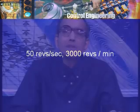And as you know, it turns out that depending on the number of poles on the generator, or the number of pole pairs, because the poles come in north-south pairs, the generator will have to be run at an appropriate speed. This is what actually happens in a generating station, and therefore there is a speed control problem at the generating station itself. The generator, of course, is not driven by a motor. The generator is driven by a turbine, a hydraulic turbine in the case of a hydroelectric station, or a steam turbine in the case of a thermoelectric or thermal generating station.